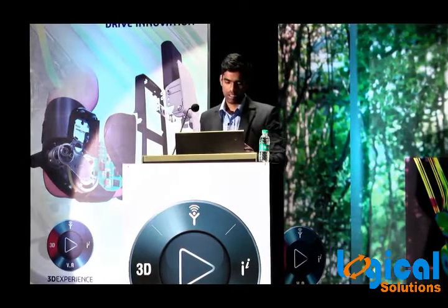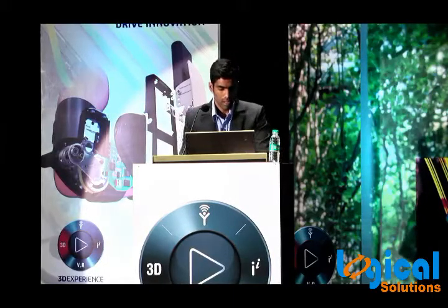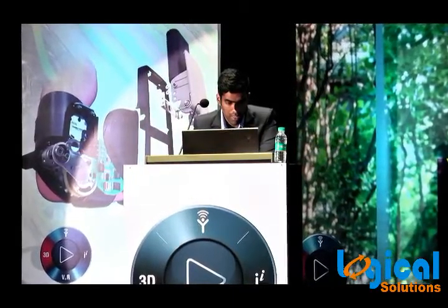And you can find one of the fillets which is missing, right? So here, about the parent-child relationship also, it is updated. You can see more information in the parent and child relationship. Most of the errors will be shown directly here in the FeatureManager design tree. And if you want to edit, you can find the edit tab directly here. So you can edit the feature directly here, and you can give the missing edges.